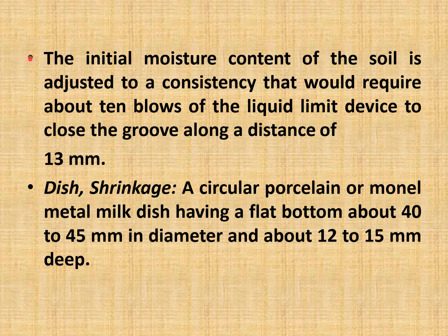The initial moisture content of the soil is adjusted to a consistency that would require about 10 blows of the liquid limit device to close the groove along a distance of 13 mm. The dish used in this test is a circular porcelain or monel metal milk dish having a flat bottom about 40 to 45 mm in diameter and about 12 to 15 mm deep.